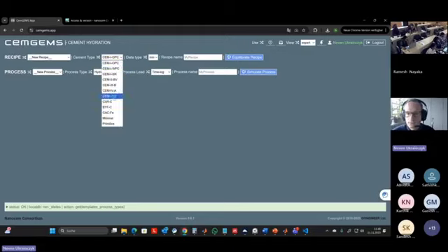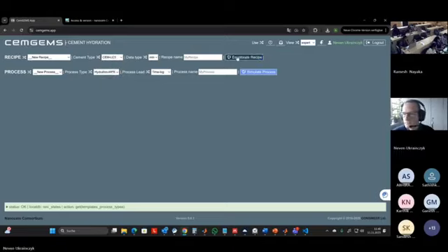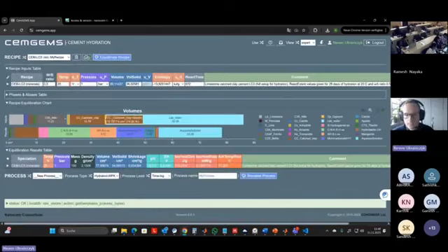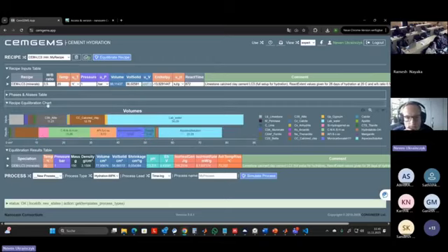So for LC3 systems, all the blended cements, you can do any kind of pozzolanic material, it's very easy to add actually. You even have calcium sulfoaluminate cements, calcium aluminate cements, different types of cements. So let's take the LC3 system. We equilibrate. We can see our phase assemblage composition after 28 days.